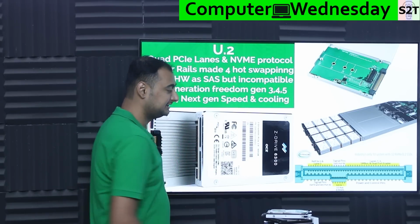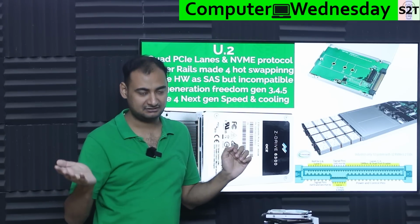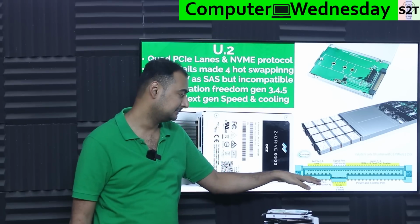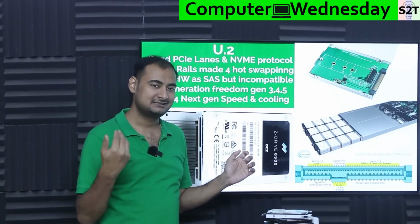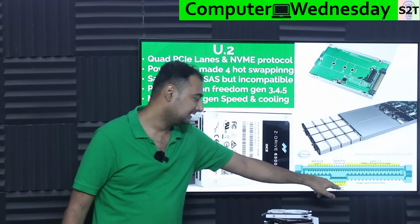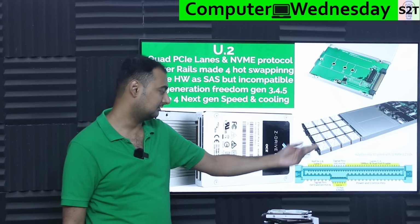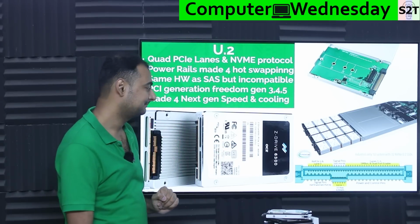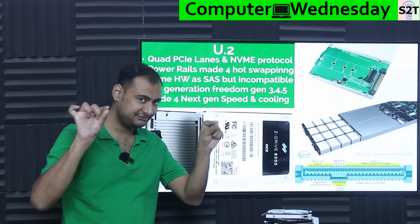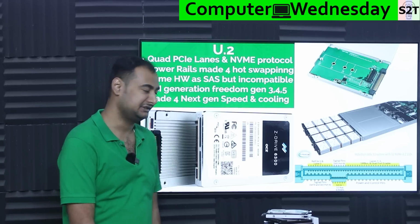You have a lot of empty space above power. Okay, instead of a one-sided connector, now it's a two-sided connector. Technically it's still one-sided data, with power on the other side. So you have PCI lanes connecting there: where SAS port B was, on the other side there is a PCI lane, and where there is a SATA signal, on the other side there is another PCI Express. That way you can use the same physical port with no fighting between each other.